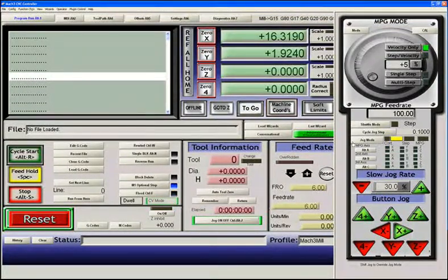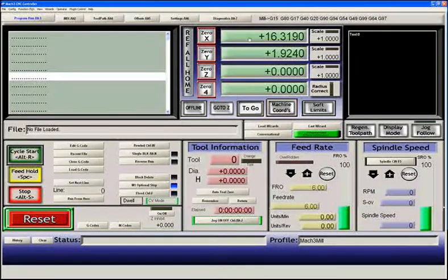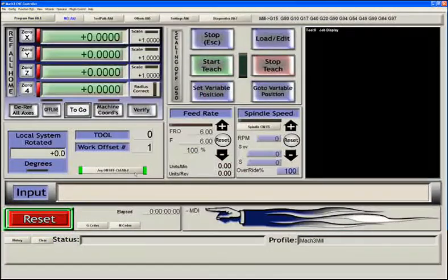The next question that often comes up is, how do I know that my axes are accurate? If I zero my X movement, and we go to the MDI screen, and we say G0 X5, you can see that the XDRO moves us to 5.000. This is correct, but many people find that their system did not move 5. In actual fact, the axis may have moved only a quarter inch, or it may have moved 10 inches. This is all set up by the motor tuning steps per inch.